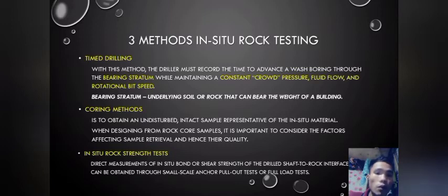Then the third, in situ rock strength test. Direct measurements of in situ bond or shear strength of the drilled shaft to rock interface can be obtained through small-scale anchor and pull-out tests or full load tests. So it uses an anchor, small scale or full load test.